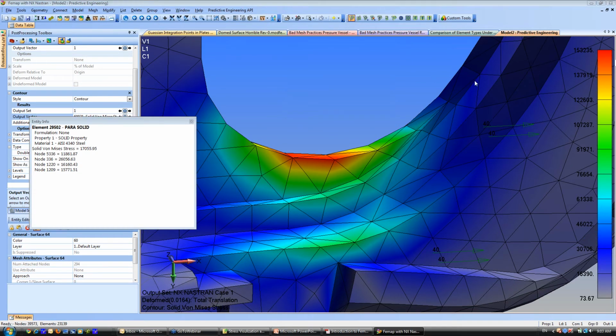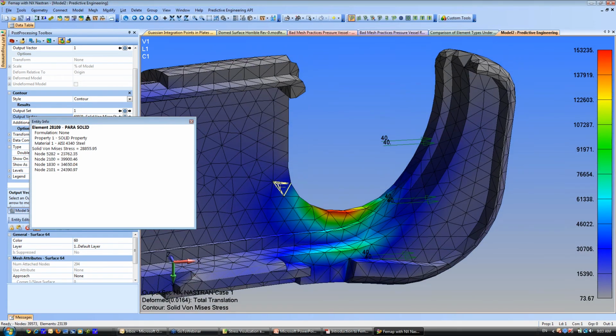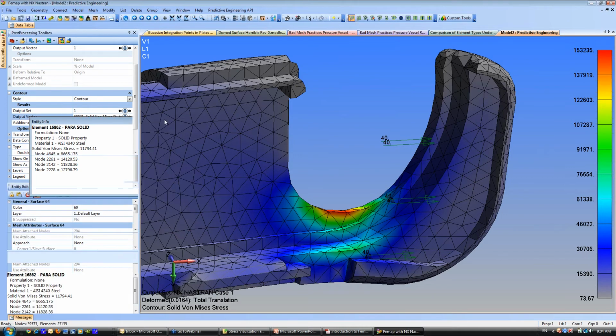But my real question, I always ask, is what is the appropriate level of accuracy that you need out of your model before we start running around remeshing and saying, we'll up the mesh density and get a better result. This is 153. What is reality? Well, reality is maybe 170, at most 170. But is it 140? No. Is it 200? No. So we can look at this knowing what we know about Gaussian integration, Jacobian, and so on and so forth. I'm going to redock this.